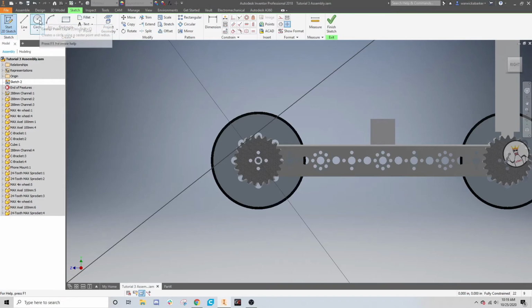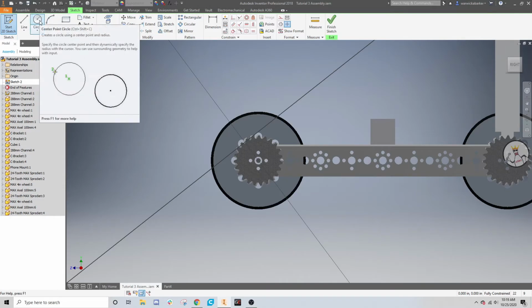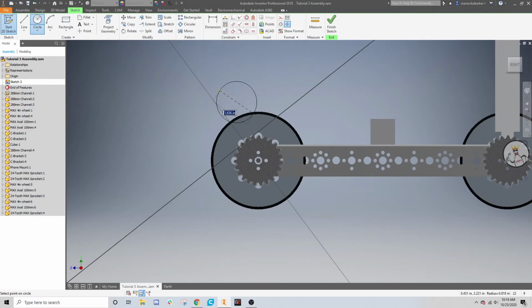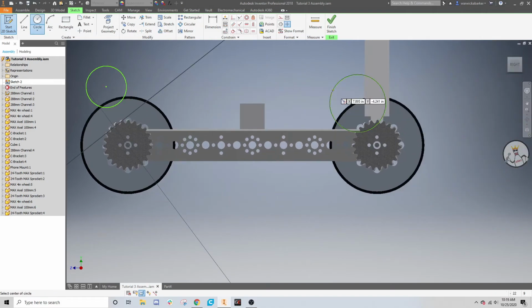So let's say we're going to make a belt placeholder, or a chain placeholder. I always call them the same thing, even though they're completely different. Which is kind of an important thing to add, because sometimes you'll have a belt or a chain clipping through a motor, and you'll be able to notice this if you add a placeholder. Otherwise, you'll have built your robot and then go to put chain on and be like, oh no, we can't do this. It doesn't fit.